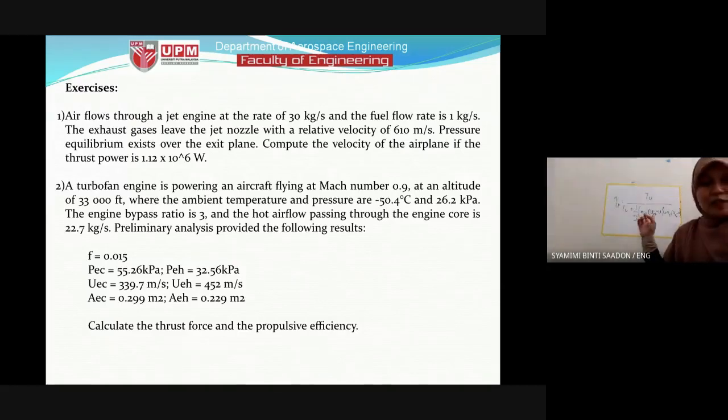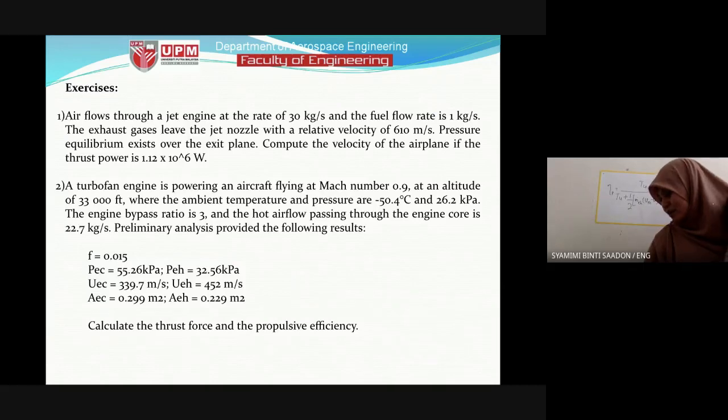So 1/2 multiplied with all of the mv squared. This is like the momentum kinetic equation multiplied by 1/2. So T we already know, the thrust force. Thrust force multiplied with the velocity U. And the rest I think we already have the values, so we can compute the propulsive efficiency.